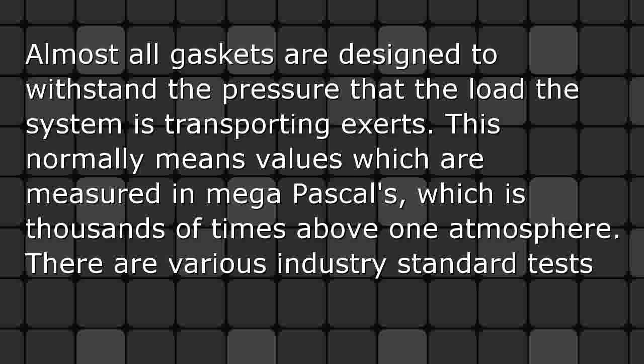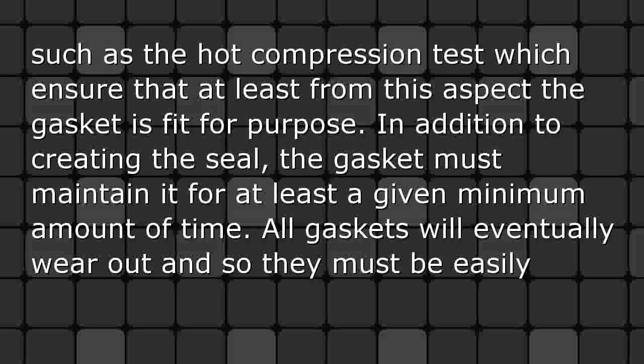What makes a good gasket? Almost all gaskets are designed to withstand the pressure that the load the system is transporting exerts. This normally means values which are measured in megapascals, which is thousands of times above 1 atmosphere. There are various industry standard tests such as the hot compression test which ensure that at least from this aspect the gasket is fit for purpose.